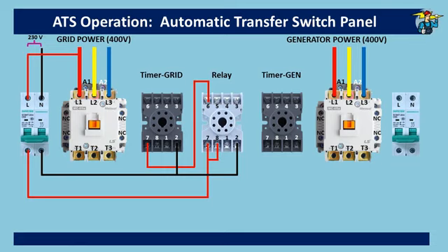Now, connect port 7 to the common port 8, thereby, after the set time delay on grid timer, outlet port 6 gets power. All what we need now is to connect number 6 of grid timer to the grid contactor operating coil A1.